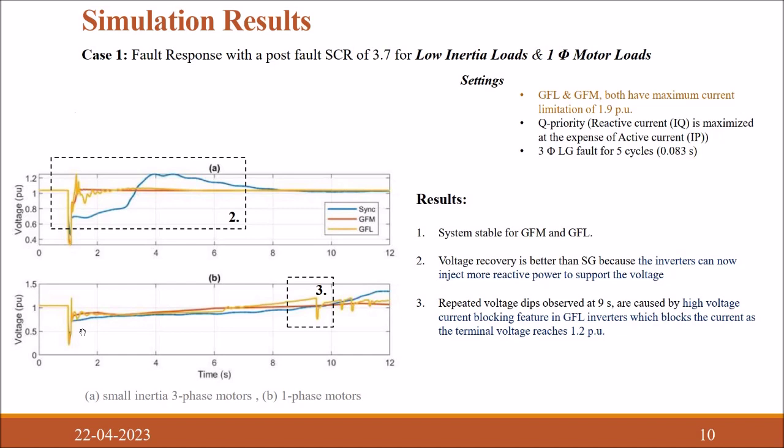We have the same reactive power priority, and a similar triple LG fault is applied at 1 second. The results show that the system is stable for synchronous machines, GFM as well as GFL. The voltage recovery is better than with synchronous generators because the inverters can now inject more reactive power to support voltage.